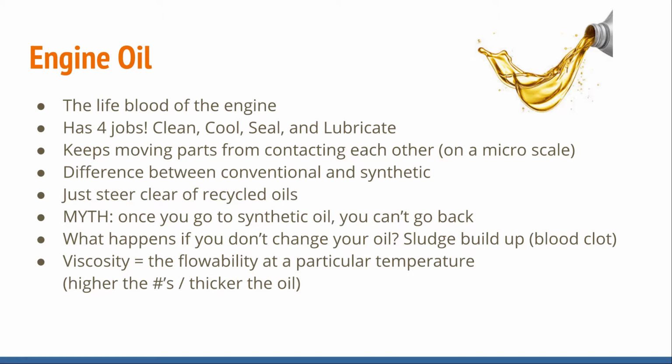So, engine oil viscosity. When you look at numbers like 10W30, 10W40, those numbers reflect viscosity. Viscosity equals the flowability of the oil at a particular temperature. The higher the numbers, the thicker the oil. Think of gear lube. Gear lube is typically 80-90, very, very thick oil. And engine oil, the lowest that I know of right now is 0W20, and that's very, very thin oil. So viscosity is the flowability at a particular temperature.